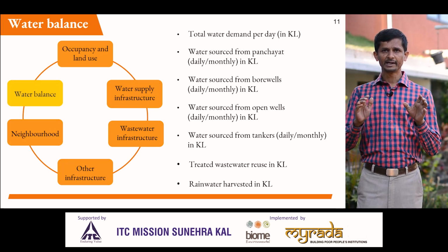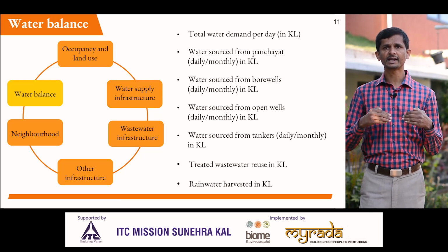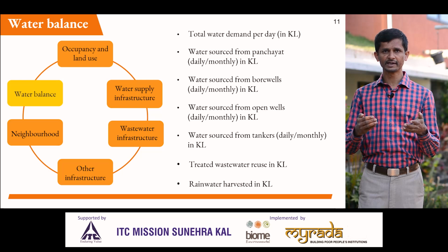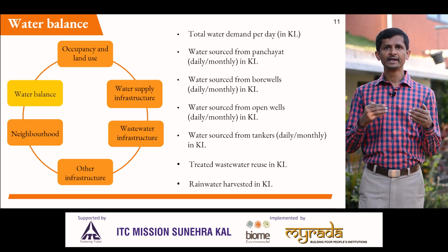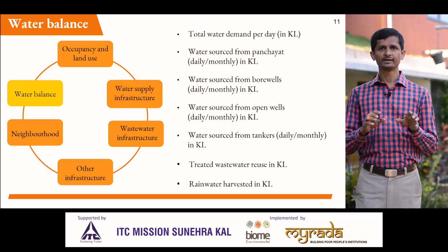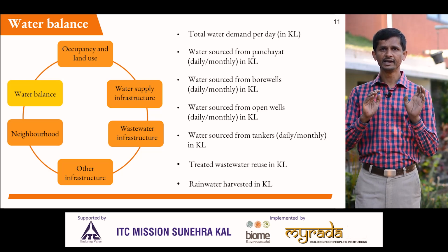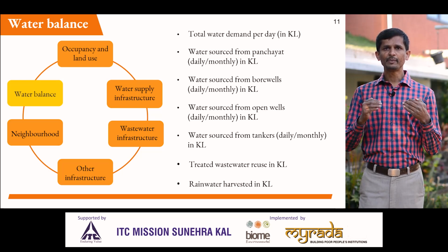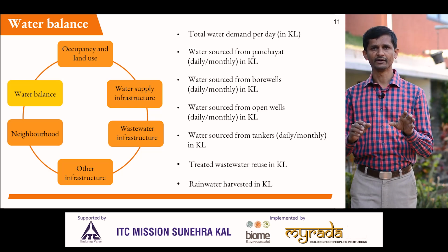Calculate your water demand, water inflow from different sources, any existing rainwater harvesting infrastructure for storage and recharge, the outflow of treated wastewater and how it is utilized, what is the water scarcity at present or the water scarcity anticipated in future when the occupancy increases. Your water balance depicts how sustainably you are managing the water in your layout.